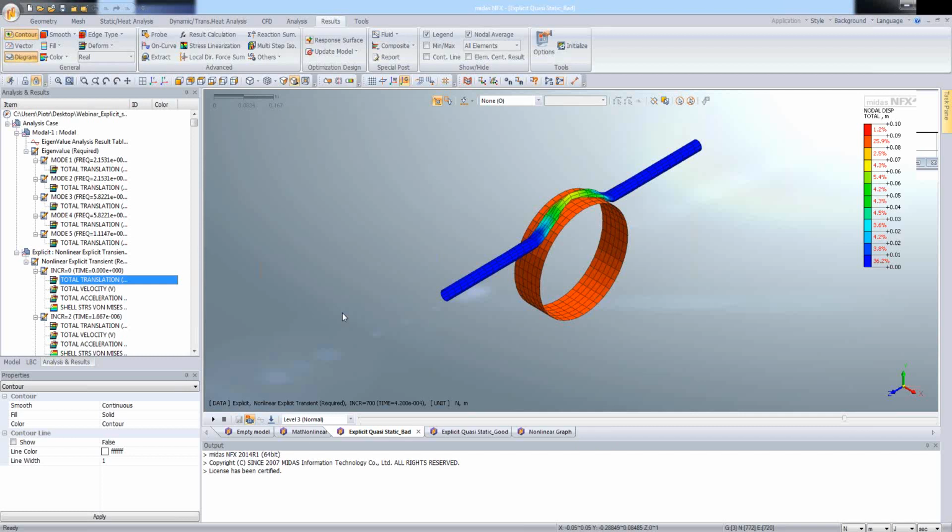It is highly impractical to model a process in its natural time, which refers to the normal modes analysis, because to analyze the static problem we need a million increments in the simulation, and due to this we want to increase the speed of the process in some, let's say, artificial way. And how to do this? So there are two methods. The first method to increase the speed of the explicit analysis is to use the proper load rates, and the second is to use the mass scaling.